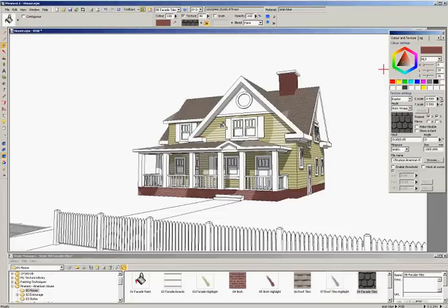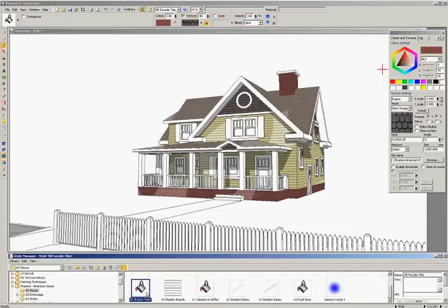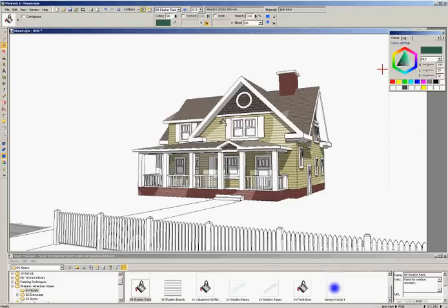Shutter paint, again non-contiguous. I've got an olive green colour, an ink mode, material locked just over the shutters, which are called in this particular instance Gene Blue, according to the model there. It's an interesting naming convention, but it just goes to show you don't have to name your model anything in particular. It could just be 1, 2, 3, 4, 5. It makes no difference as long as there's an identifier for that particular material. It really doesn't matter what you call it.